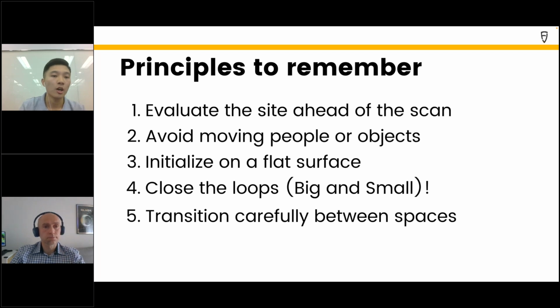Third, both S1 and P1 actually contain an inertial measurement unit, known as the IMU, that can help the scanner understand where it's facing, the angle, and the orientation. So that's why it's important for you to initialize the scanner on a flat surface, so that at the beginning of the mission it can register the correct information to avoid errors in the final point cloud model.